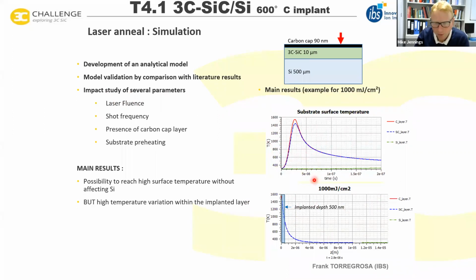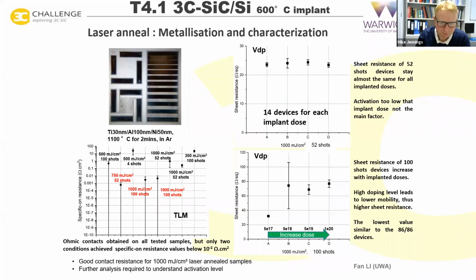It doesn't get through to the silicon lattice, because you can see here the same profile as a function of depth, rather than time. And we can see that we're nowhere near the silicon layer, because don't forget, the silicon carbide epi layer is about 10 microns wide.